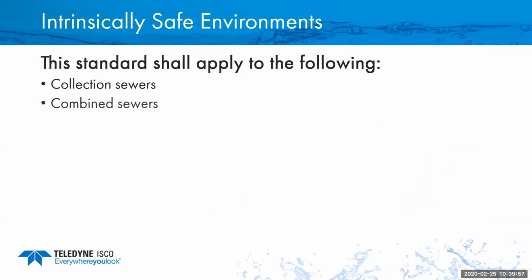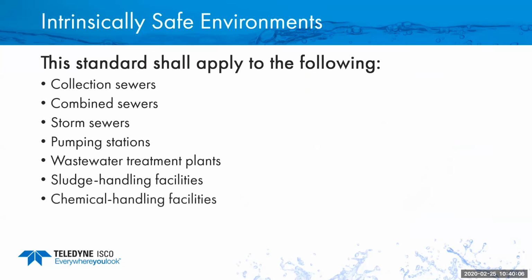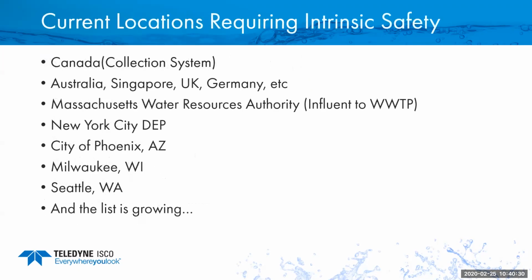Okay, so intrinsically safe environment. That applies to anything in collection systems, combined sewers, storm sewers, pump stations, wastewater treatment plants, sludge handling, chemical handling facilities, and treatment facilities. So we are now able to work in a lot more applications than we were prior to having the EX. A lot of wastewater plants, influent to the plant is almost always a hazardous location. So while we don't see this 100% everywhere, it is gaining in requirement.